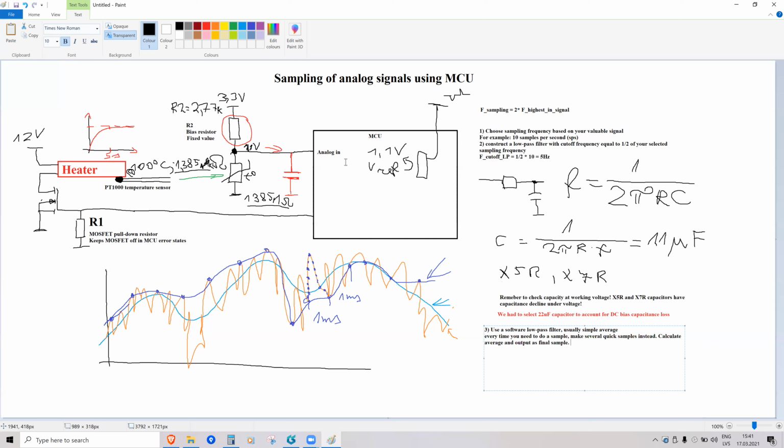So 10 samples would only take something like 100 microseconds. So it's 0.1 millisecond, and you have a timer every 100 milliseconds. So taking 10 samples asks for very little time, but you can do it. And then you calculate the average and you will filter out these small spikes or some higher frequencies that get through.